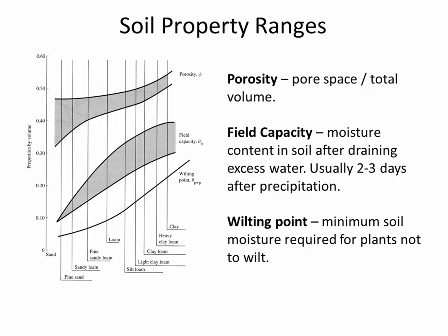And so porosity, this first property, there's a range of typical values. And so the reason why there's two curves and they both go with porosity is that one is the upper limit for typical porosity and one is the lower limit for typical porosity. The interesting thing, which is counterintuitive, is that I tell you soil holds on to the water, and so maybe you'd think that means there's fewer voids. But actually clay has more voids than sand does.